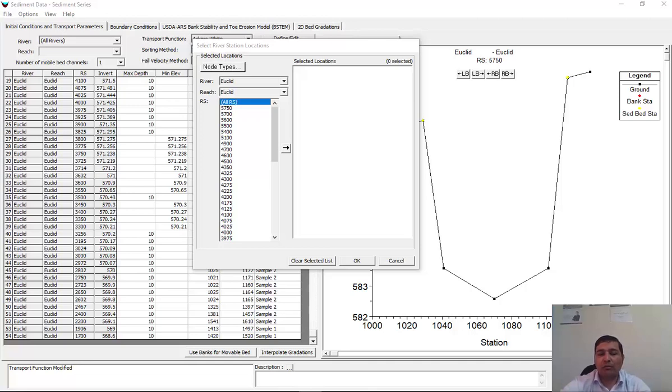Pass-through nodes are one way to mitigate artificial pool deposition in HEC-RAS. Making pool pass-through nodes keeps them open. Pass-through nodes don't erode or deposit. Turning bed change off can seem like an aggressive solution to a numerical artifact.